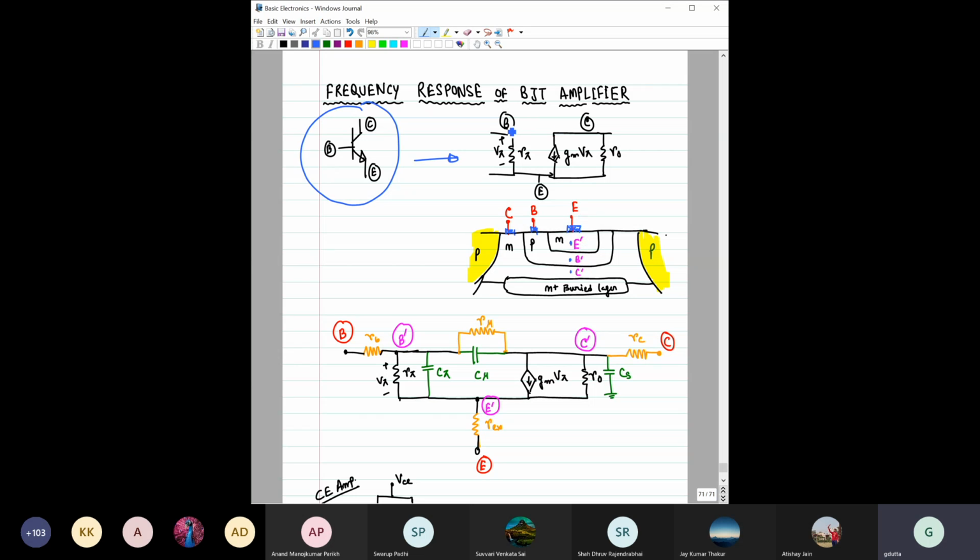So far, what we have considered here is basically this part. Now, if we have to include in our analysis the other part that we have not considered so far, then obviously we have understood that with this emitter we should include one resistance, right? This is the emitter terminal E dash inside, and this is the external terminal. So between them we should have a resistance because of this contact. Fine. From this B dash to B, there should be one resistance.